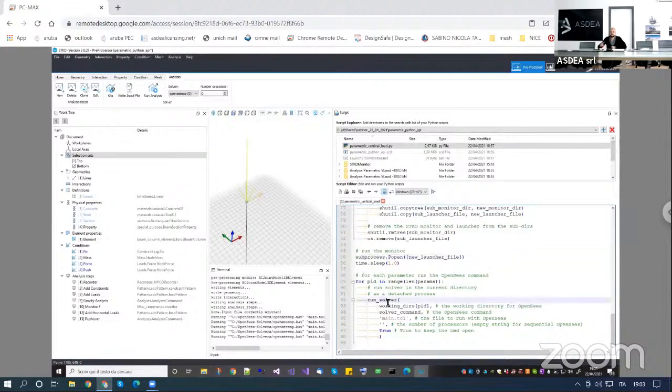So it will not be a parametric analysis in the sense that you run all the parameters at the same time, you run it one at a time, but the nice thing is that you can do a click and wait for all the analyses to finish, okay? So every large model will be run one by one. When the first finishes, the second one will be launched. But the nice thing is that you don't have to go inside STKO every time and change some parameter, okay? So you can do it all at once and wait for OpenSees to finish. So it still has some usage cases.